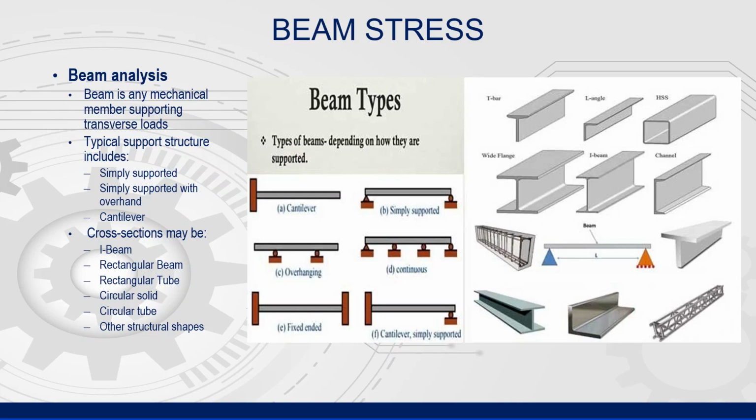Also note that cantilever and simply supported beams are statically determinate, meaning they can be solved via equilibrium equations. Fixed beams, along with overhung and continuous beams, are statically indeterminate and cannot be solved with equilibrium equations. Generally, we will use beam tables and charts in these instances.